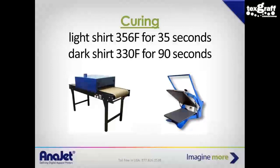All right. Then there's the print process. Put the shirt down, align it according to the grooves and the markers on the platen, or use the appropriate platen, the sleeve or youth size platen or half platen. Use the appropriate platen based off what you're trying to print on. Then hit the green button, print it out, and take it over to your curing section, which is your heat press or your tunnel dryer. Most commonly, like I said, is the heat press.